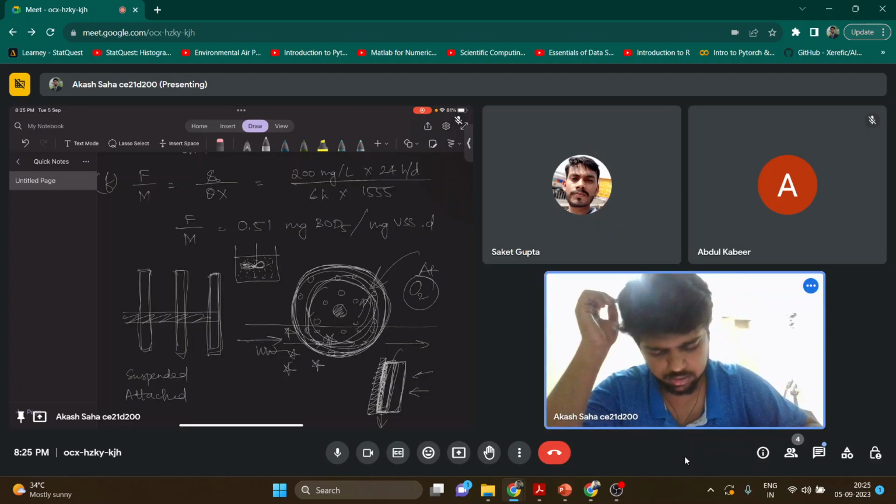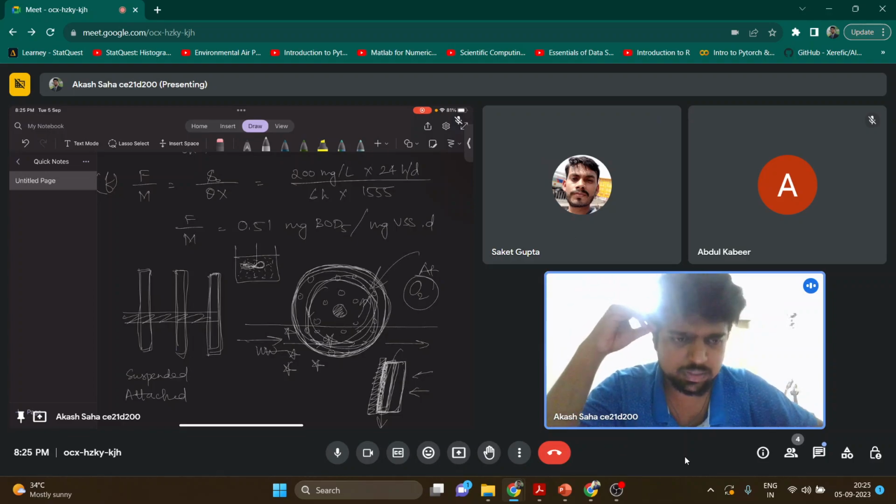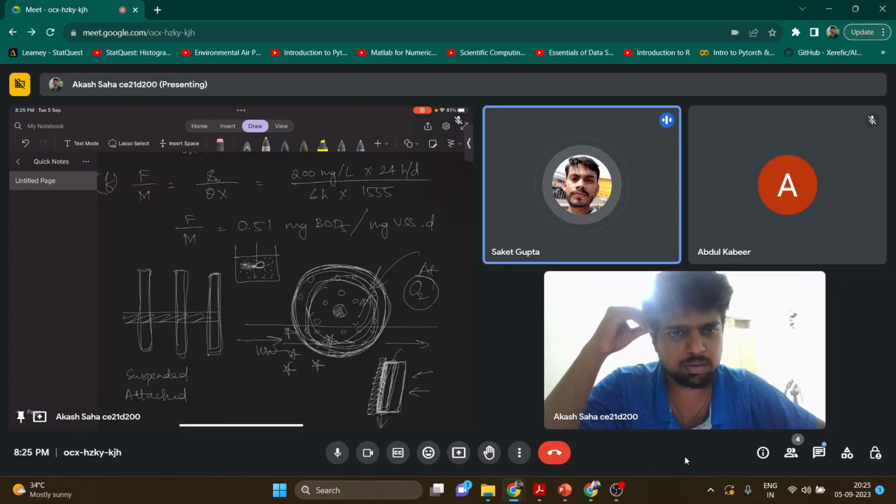No, see, it depends on what type of system you are designing. Suppose you are designing a conventional plug flow type reactor, then the theta c should be 5 to 8 days. And then here our HRT is less than 4 or more than 6, so it means our calculation is wrong.